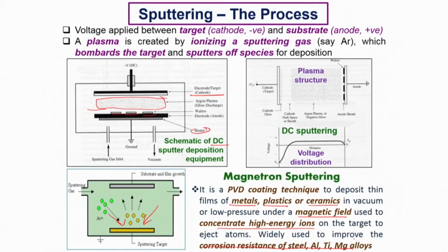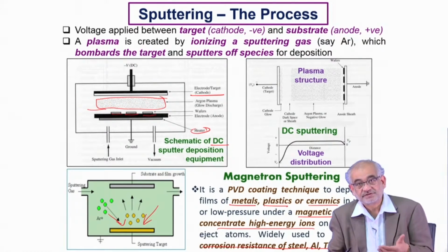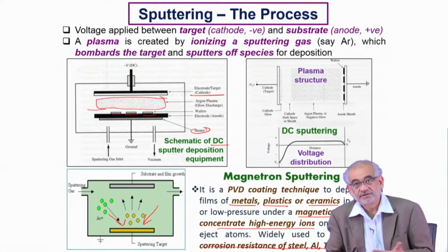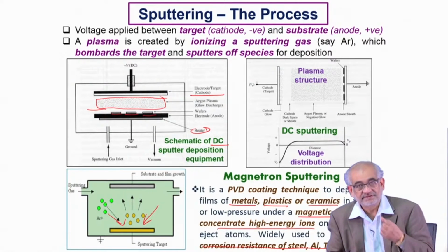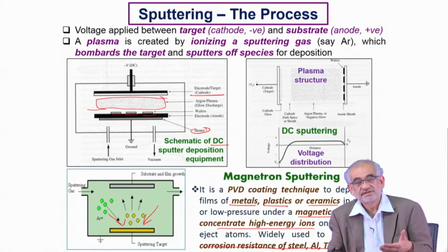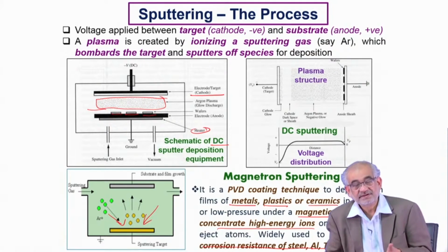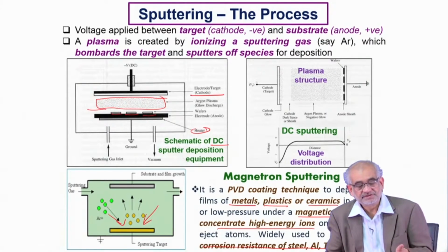You can even create it just as a possible substitute for, let's say, galvanizing. You can create actually a cathodic or an anodic layer to prevent corrosion and oxidation, but very thin. And the other advantage is that you're not exposing to any aqueous bath, you're not subjecting to any high temperature, you're doing more or less at room temperature, and most importantly, you actually are able to maintain a very thin, precise layer.